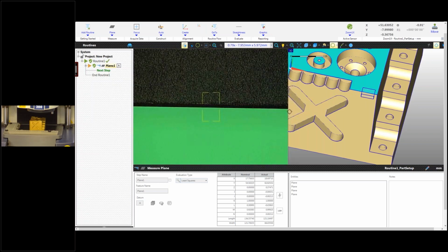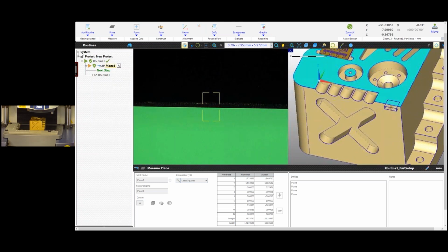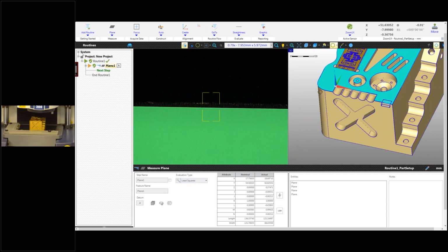But now I can set some lighting, and I want to use this front edge here as my B datum, okay? And so, as you all know, if you've been through any of my QBI classes, OGP classes, MeasureMind, MeasureX, what do I want my backlighting at if I'm going to measure an edge? About 50%, give or take 10%. Turn those top lights off. If you have the top lights on, it's going to confuse the edge finders, so let's turn those off.